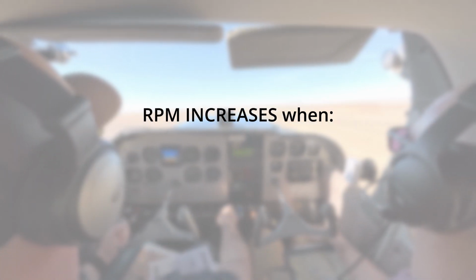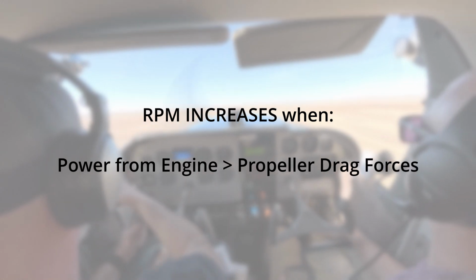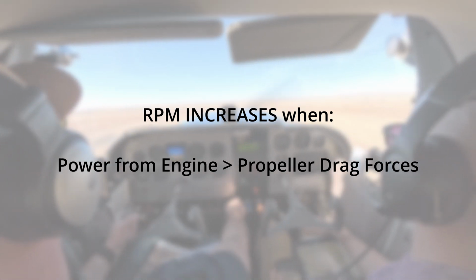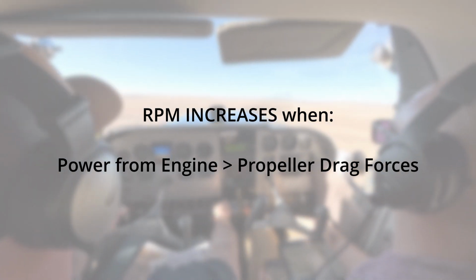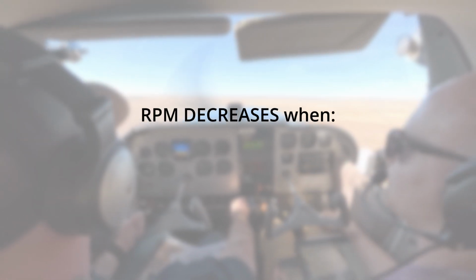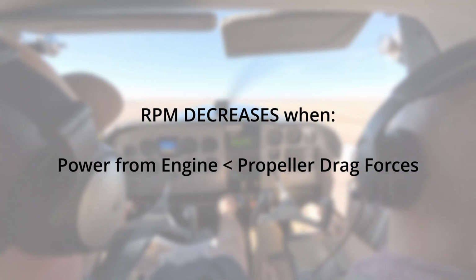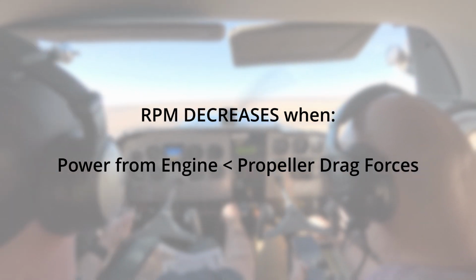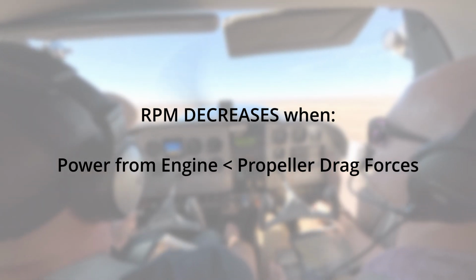To increase RPM, we need an excess of power from the engine for the amount of drag that's present on the propeller. This excess power overcomes the drag force, allowing the propeller to spin faster until the forces are balanced out again. When decreasing RPM, there is an excess drag from the propeller for the given power on the engine. The excess drag slows the propeller RPM until a balance is achieved.